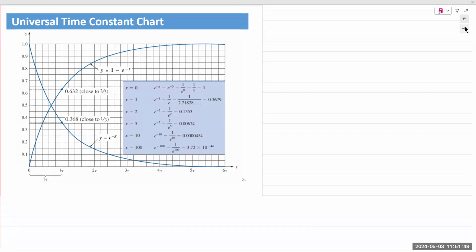Let's look at what happens when you plot these. Exponential relationship. The value of the inductor does not matter. The value of the capacitor does not matter. The value of the resistor does not matter. The value of the source or the energy does not matter. That will only change the level. The relationship always, always, always stays exponential. This is for charging. And this is for discharging. All equations with e raised to minus t over tau always have an exponential relationship. That does not change.